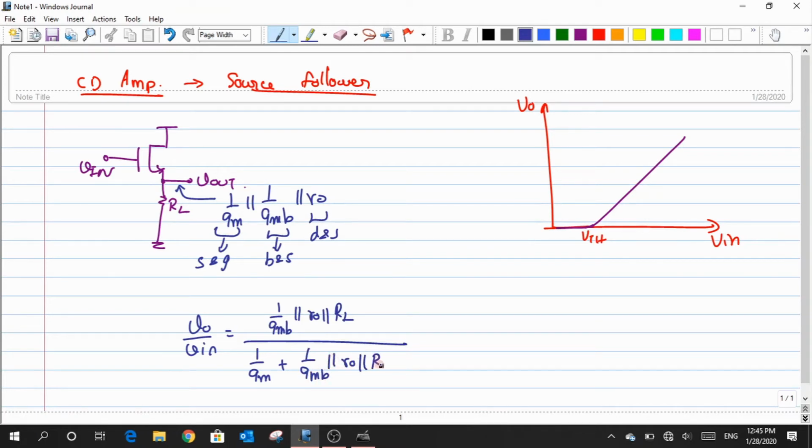Yeah, so when I look into this formula, I couldn't get the entire insight into this particular formula. So what I do is that I'll just try to combine each of these 3 parallel resistances as a single resistor value. Let me label that as RL prime. RL prime is nothing but this entire quantity that I have in parallel, divided by 1 by Gm and then RL prime.